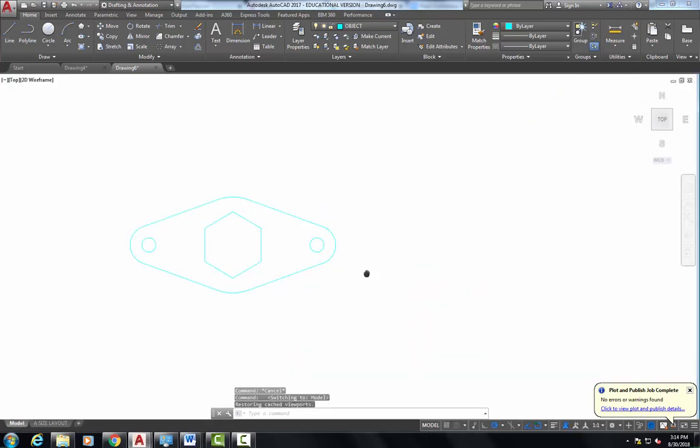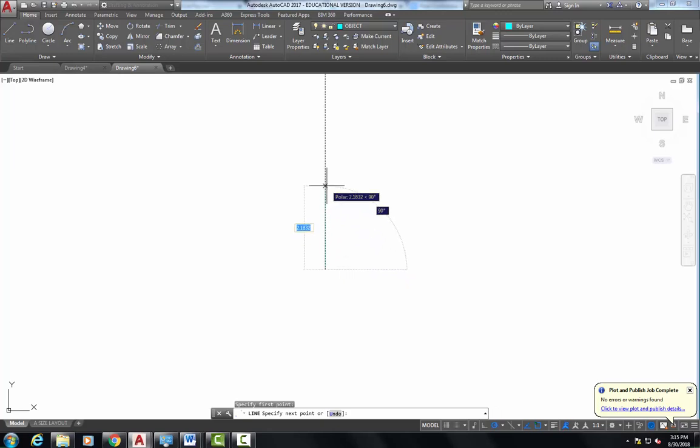So I'm going to go back to model space and just shift that off to the side. When I'm dealing with 7-7, I can see that that's basically 4 of the same thing all around a central point. So I could probably create one of those, and then I could array it, which we've done just a little bit with, and get all 3 of them, or all 4 of them. So I'm starting at what would be the center of this object, and I can see that it's 2.5 inches to one edge or to the top. So I'm going to go up 2.5,